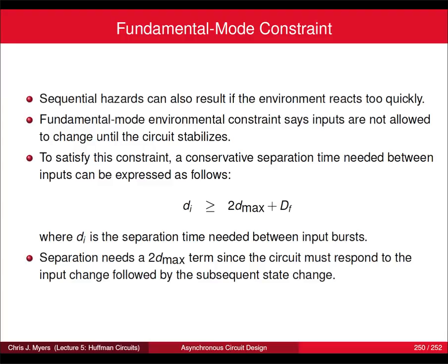Okay? So I've told you a lot of positive things about burst mode circuits, right? One of the positive things is, the input form looks like state machines. It's very similar to synchronous design. It can use some minor modifications to state minimization. You do need to do critical race-free state assignment. Logic synthesis, you have to remove hazards.